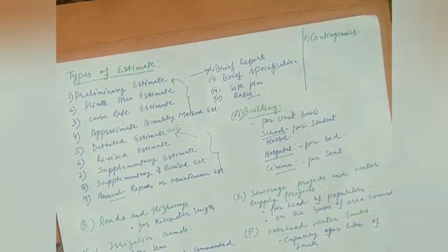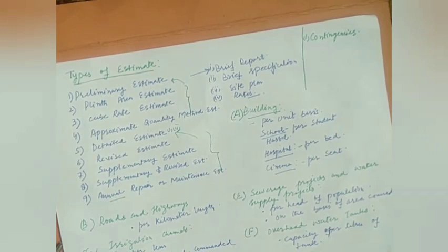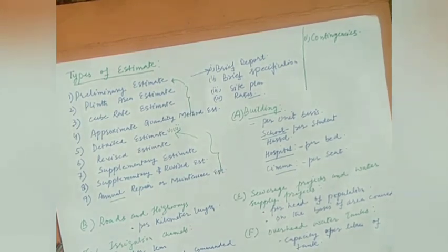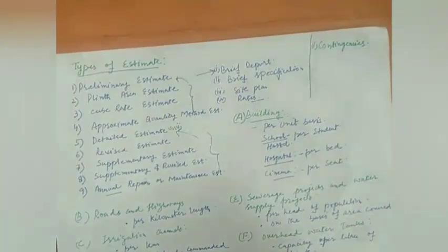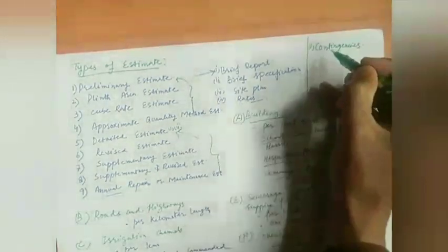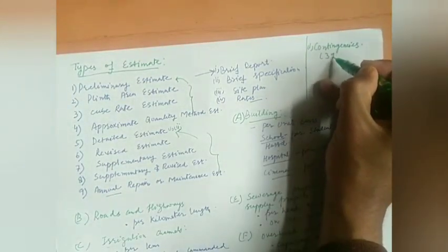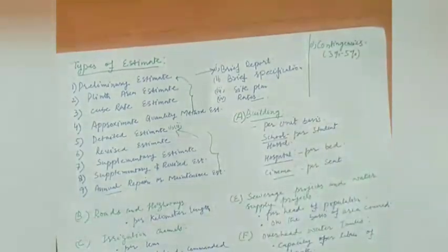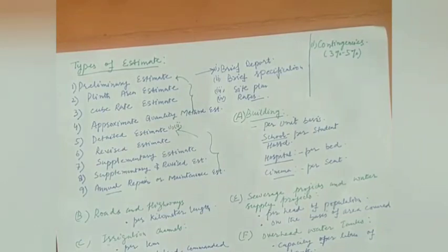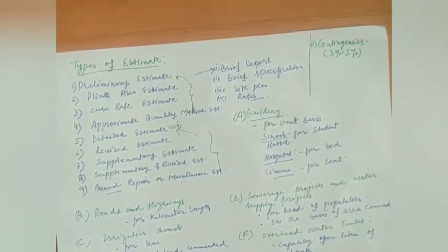These expenses cannot be classified under any separate item or subhead, yet they pertain to the work as a whole. For these types of expenses, a provision of 3% to 5% of the total cost should be made.